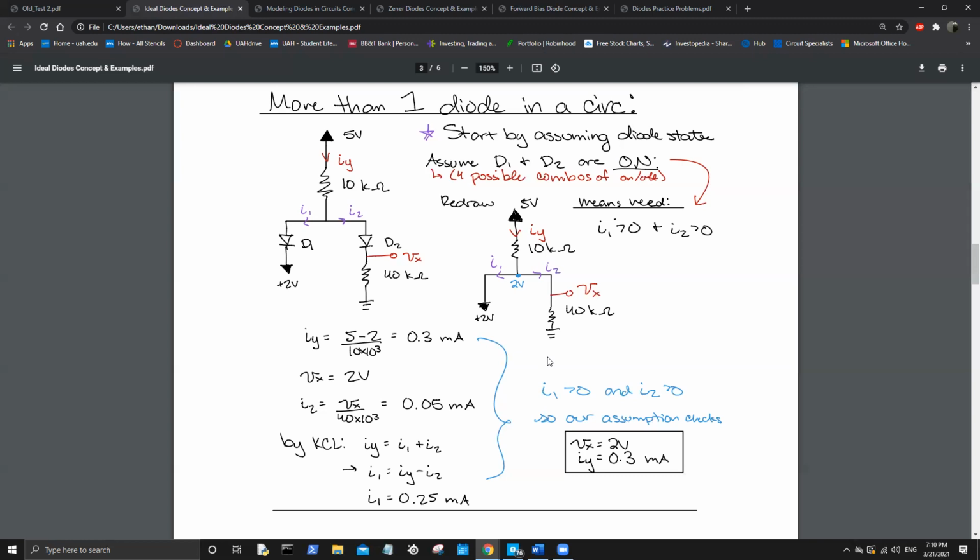In real life, if you're expecting 2 volts out of something, a 0.7 voltage drop is a significant chunk. I would change VX from 2 to 1.3. Yeah, that drops VX hard. So that's important. In real life, sometimes the assumptions you make aren't valid, and they will ruin the thing you're trying to build.